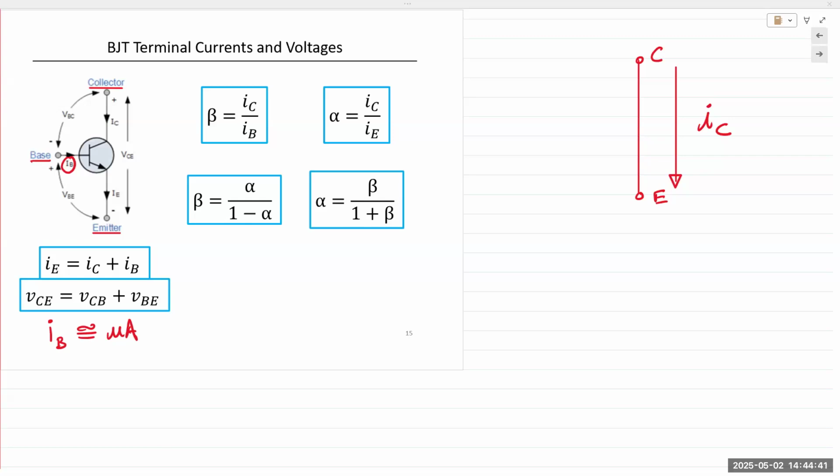So if you have a unity gain amplifier, the voltage is not being amplified, but the current is being amplified. You have a small amount of current entering with a small amount of voltage. The voltage is basically the shape of the waveform. The shape of the waveform is transferred exactly as it is to the output, hence unity gain. Gain in that sense is simply V out over V in. So V out over V in is equal to 1, but the current gain is far higher.